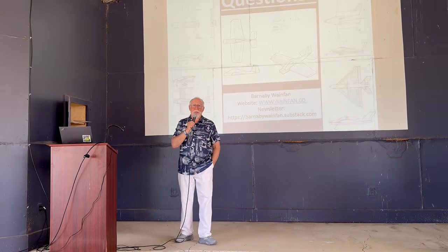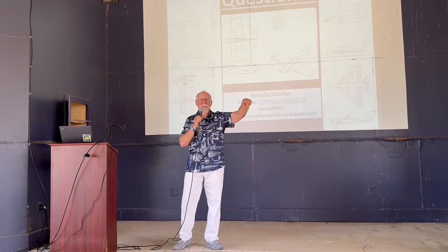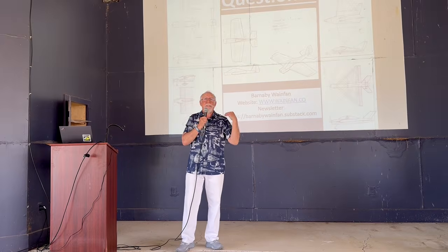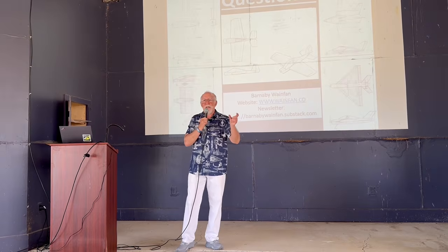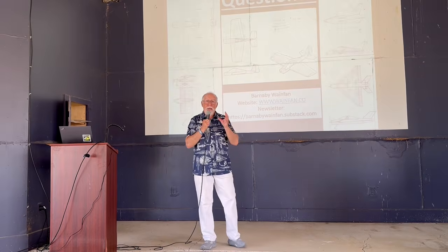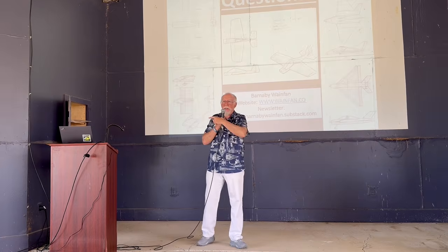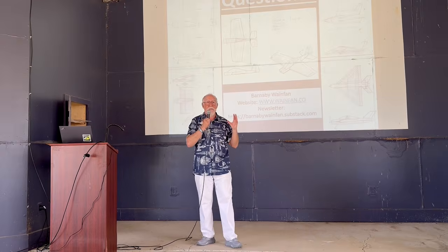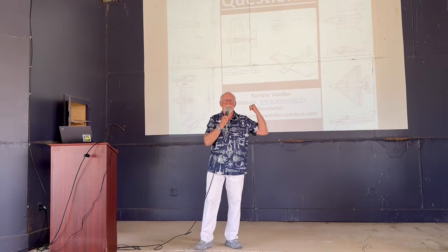Well, on the tailless airplane, the aft limit is set by where the aerodynamic center of the basic planform is. There's nothing I can do to adjust that. The forward limit is set basically by the control power of the elevons. And so tailless airplanes, it's harder because you don't have the variability of the horizontal tail, and so your limits are tighter. And in fact, that's one of the reasons the conventional wing body tail has lasted so long, because you have that degree of configuration flexibility to do something like I just showed you with the scissor plot.